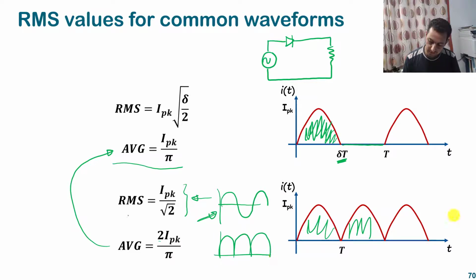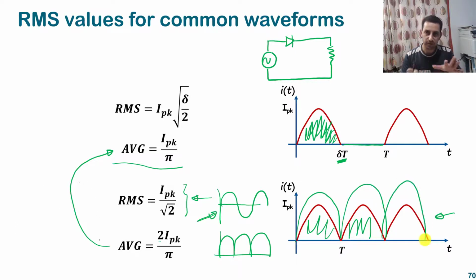And if I square this signal, it will look like this, with some differences, I just approximate the squaring, since the sine wave and sine square are a little bit different, but this is just approximation. So both of them are similar with the same peak, so that's why they have the same RMS value. The conclusion here, if you have two signals that are different originally, but when you square them they are identical, the RMS value will be also the same.